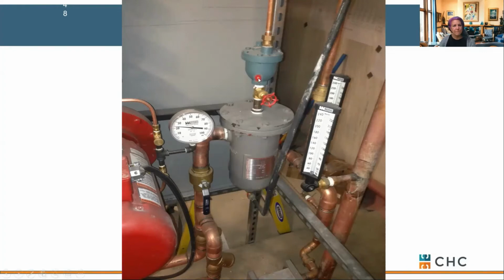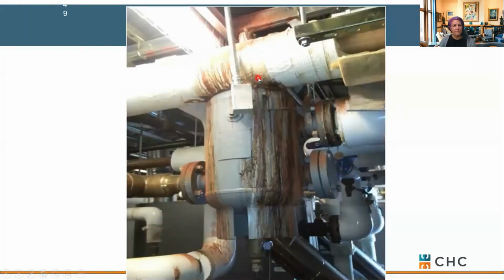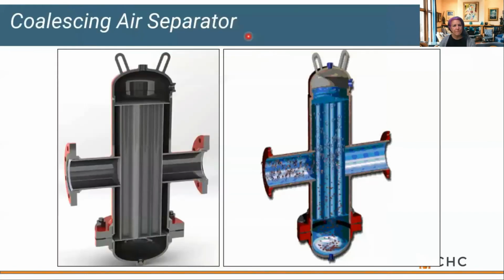This is your high capacity air vent. Sometimes guys are doing chemical flushes, and that plays havoc with your automatic air vents. But typically you're going to hear an air vent burp a few times when you start up your boiler, get rid of the air, and then that's it. You're going to run quiet the rest of the day. So that was a tangential style.